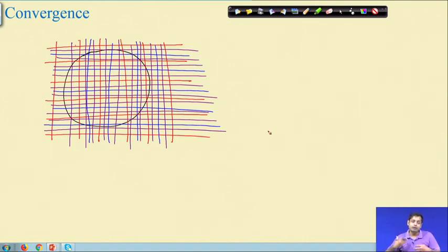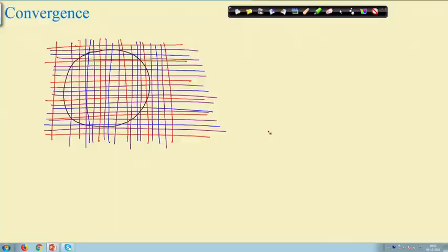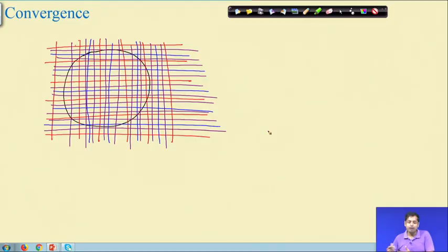If we keep reducing the size of the squares, the number of elements increases, and you also get better accuracy in the context of this problem. If we plot the number of elements on the x axis and the computed area on the y axis, we will see that as the number of elements becomes larger, the computed area approaches the exact value, right.